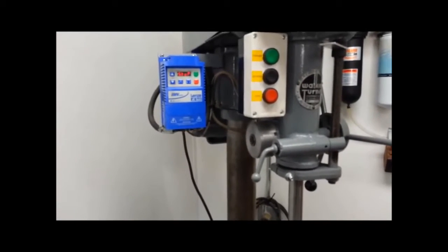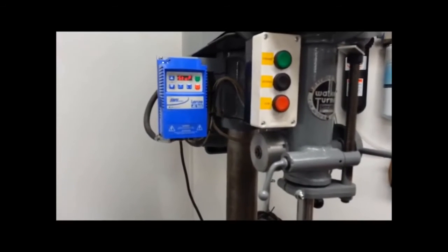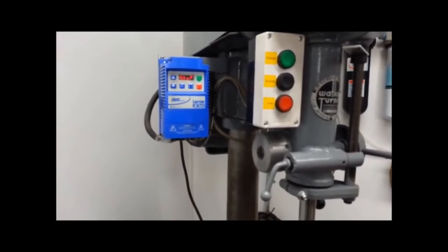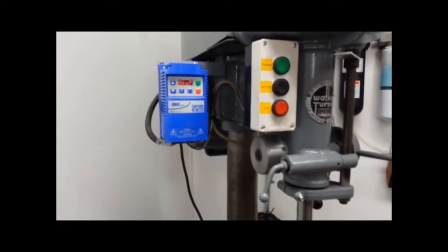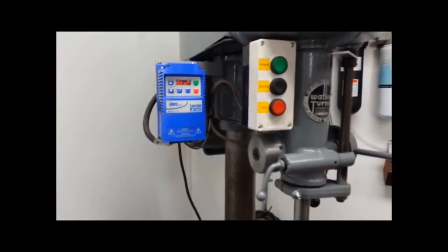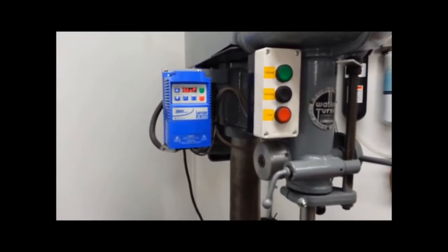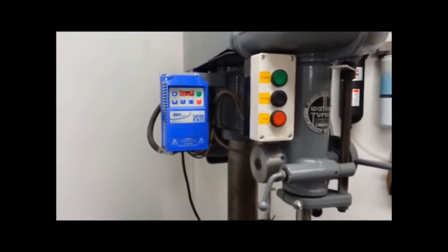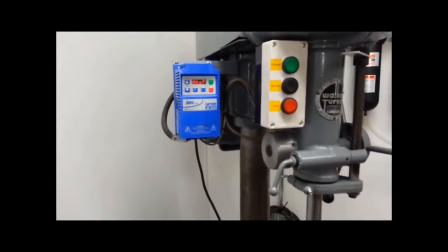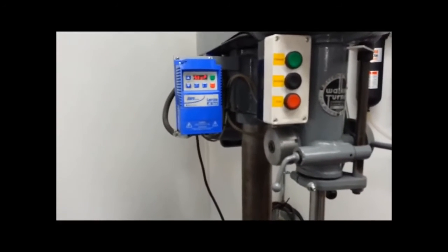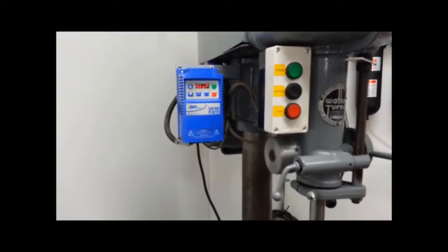If it doesn't say SFA on it somewhere, service factor amps is very easily calculated. You take your running amps or your standard amperage and you multiply it by the service factor of the motor. Now the service factor on the motor is going to be 1.15, 1.2. I've seen them as low as 1.10. So you take your standard running amps, multiply it by your 1.1 or your 1.15, and that's going to give you your service factor amps.